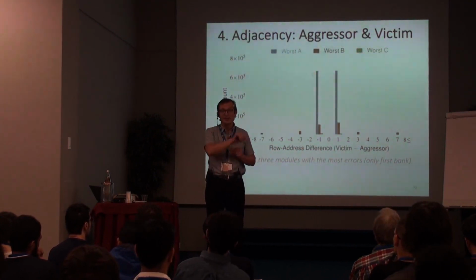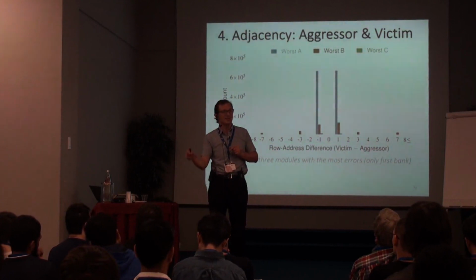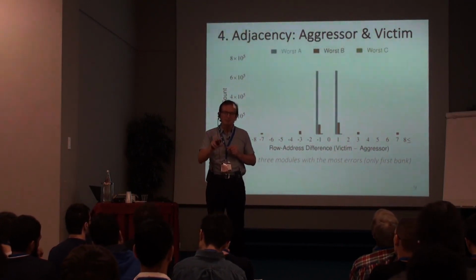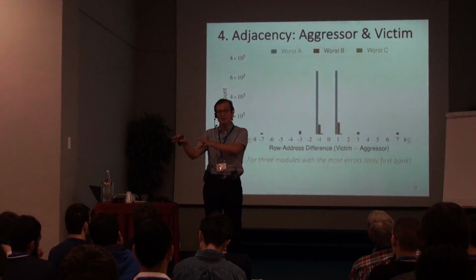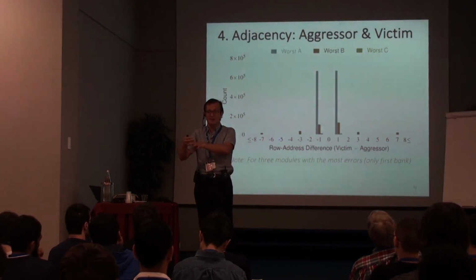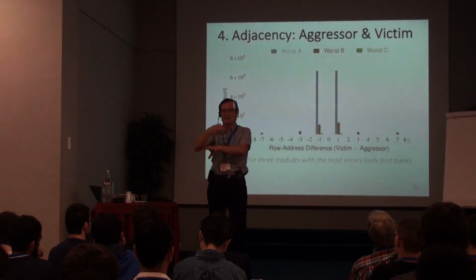But where does the memory controller go is now a good question, right? Should it be a separate chip? That's a lot of communication overhead. Should it be on the processor? Now it doesn't know enough about DRAM. There needs to be a protocol, but it can discover a lot. Should it be on DRAM? There are also benefits to this. Now it doesn't have enough information from the processor, right?